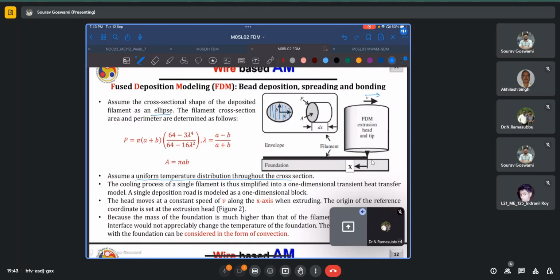So I can estimate that if I take the temperature readings at say 3 points, it can be reasonably assumed that T1 would be greater than T2 would be greater than T3 because T1 is the most recently deposited one. It has not had as much time to cool than T2 or when compared to T3.